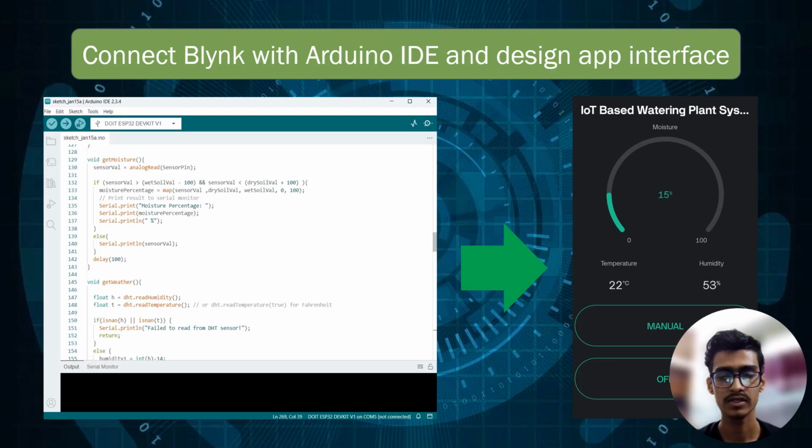We faced difficulty while connecting the ESP32 and Blynk with the Arduino IDE. We had to install a driver for the ports, and we also had to install libraries like the DHT sensor library and the Blynk library. There were other libraries that we had to install too. Then we were able to connect all the circuit together. And also, we designed this beautiful app interface.